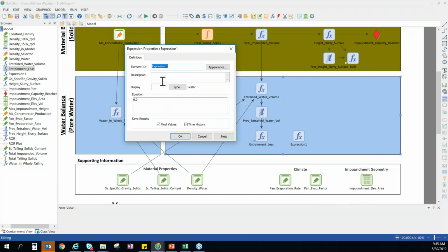And our evaporation is also going to be a function of this pan evaporation factor. If you're familiar with hydrology and evaporation calculations, typically we take a pan evaporation rate and reduce it slightly to account for actual conditions that are not quite the same as the idealized conditions within an evaporation pan. So I've brought this in. I think I use a value of 0.8, just a generic number, and for the pan evaporation rate, I think I assume 5 millimeters per day. So decently high evaporation.